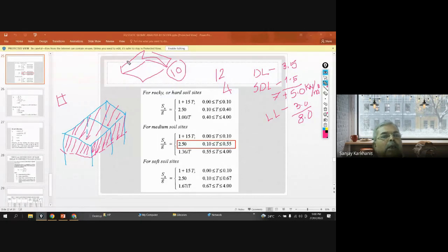So that calculation of weight of beam, weight of column, then weight of 50% masonry below and 50% above was approximated as 12 and 4 and 10, and whatever live load, I think it was 3. So 10 for roof and 12 for floors was considered over here.